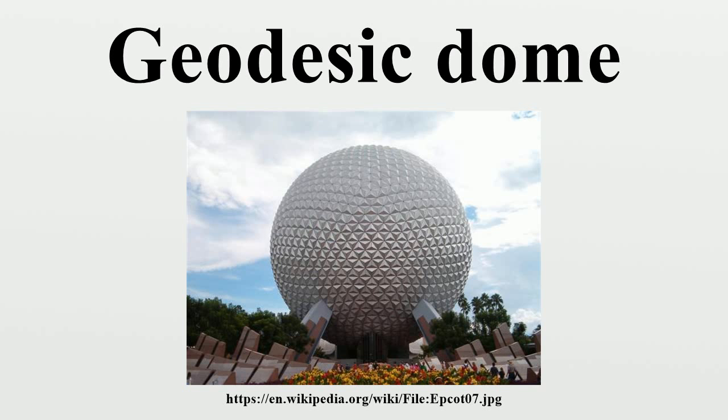In 1986, a patent for a dome construction technique involving EPS triangles laminated to reinforced concrete on the outside, and wallboard on the inside was awarded to American Ingenuity of Rockledge, Florida. The construction technique allows the domes to be prefabricated in kit form and erected by a homeowner. This method makes the seams into the strongest part of the structure, where the seams and especially the hubs in most wooden-framed domes are the weakest point in the structure. It also has the advantage of being watertight.